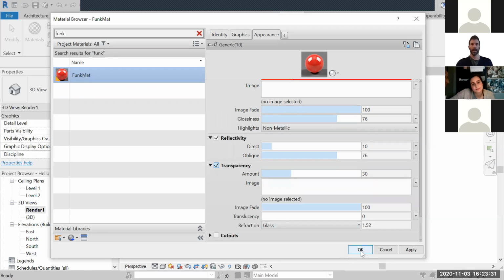And I'll talk about this in another class. What if you want a semi-translucent or whatever material? Then what you need to do is a partition made of only 1 layer. Call it probably a glass or translucent glass, and then change the transparency settings for that particular material. So the amount of that transparency will be pretty much the translucency.